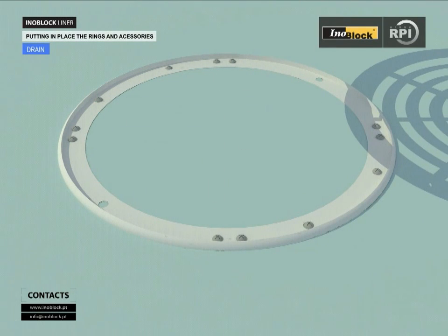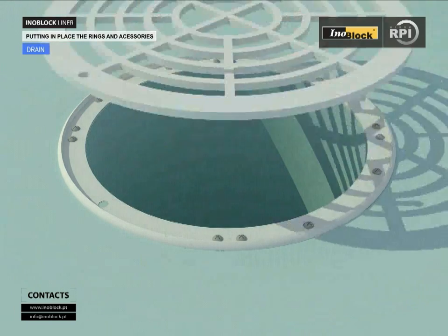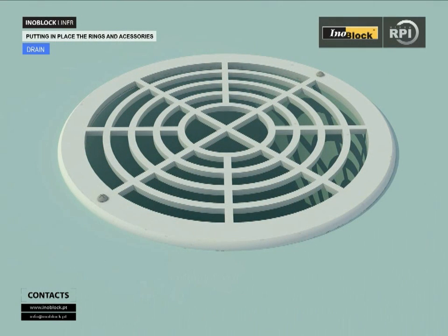Fill to a depth of about 20 centimeters and continue to remove any wrinkles which may still be in the liner. Shut off the water and fit the drain securing ring with the screws provided. You can then cut out the circle of liner with a sharp knife and fit the drain cover. Care and attention are required when cutting out the liner.